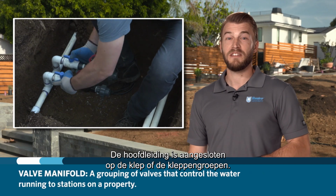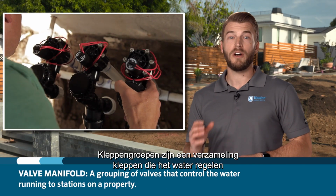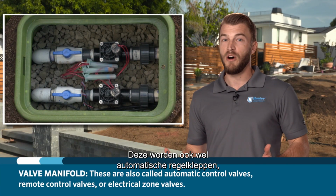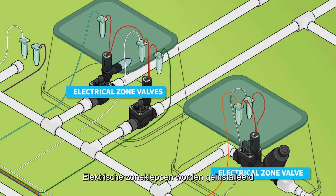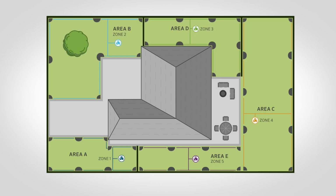The mainline connects to the valve or valve manifolds. Valve manifolds are a grouping of valves that control water flowing through the zone or stations on a property. Sometimes these are called automatic control valves, remote control valves, or electrical zone valves. Electrical zone valves are installed to control the water flow to the sprinklers in each zone.